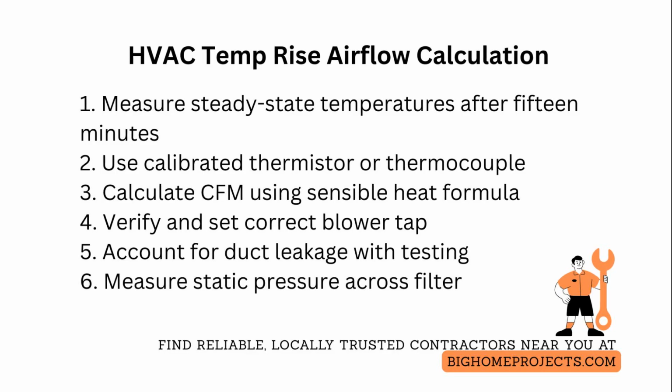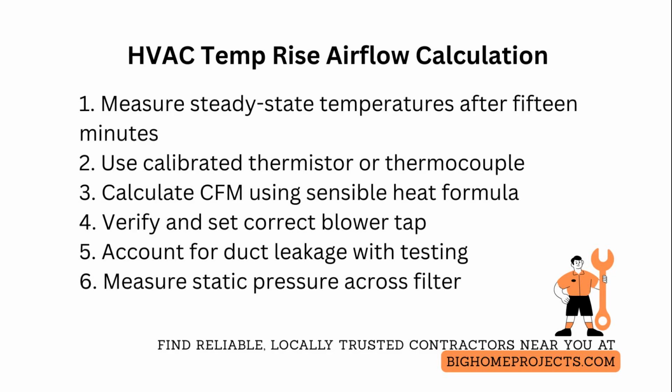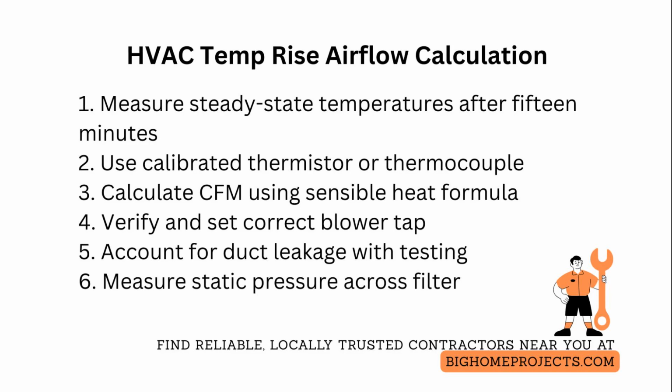CFM equals sensible heat divided by the product of 1.085 and the temperature rise, where sensible heat is the burner input minus estimated combustion losses for gas or the rated heat output for electric. For cooling, use the measured sensible cooling in British thermal units per hour.